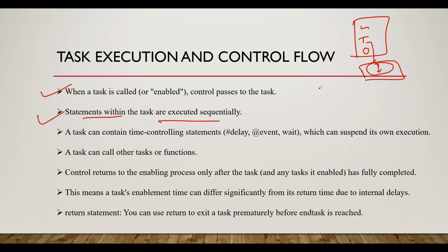Also keep this in mind, here there is no need to add a begin end block. It will automatically execute your statements sequentially. Now your task can contain timing control statements. I have already discussed these: you are adding some delay or waiting for an event. These timing controls add time delays in your task, which can suspend its own execution.